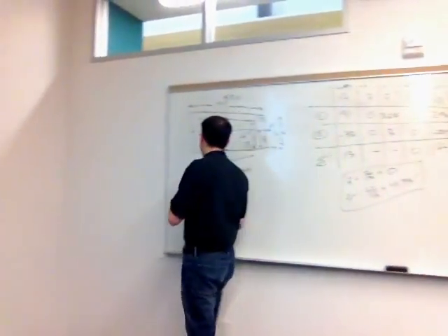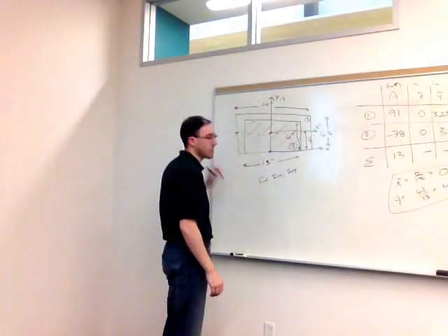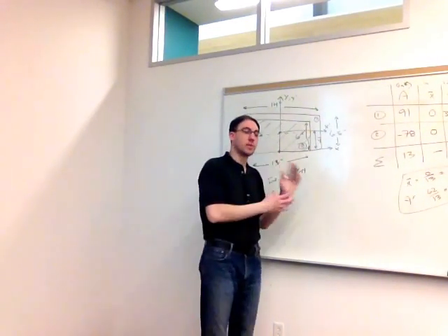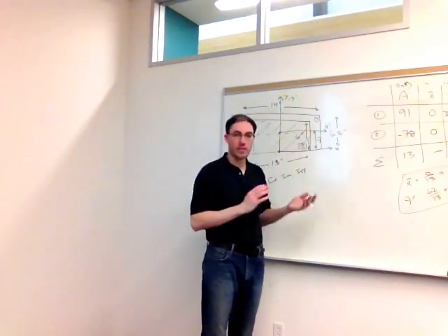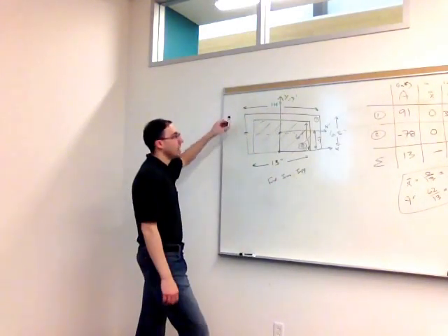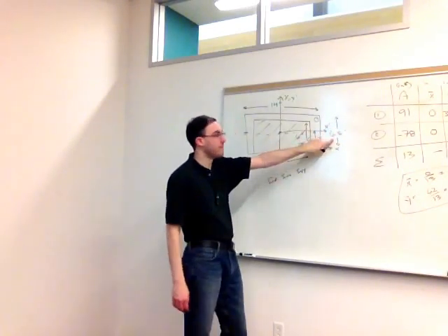So when I'm talking about Ixx, that is its resistance to bending around the horizontal axis that passes through the shape's centroid. And again, this will tell us which dimension is being cubed, if it's a rectangle or a triangle, and which is linear. For shape number 1, its Ixx, we're going to cube this dimension, the 6.5.